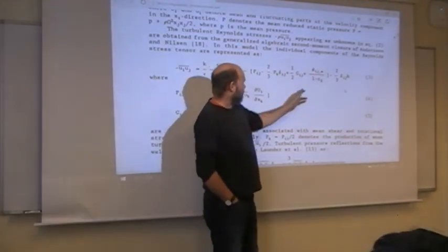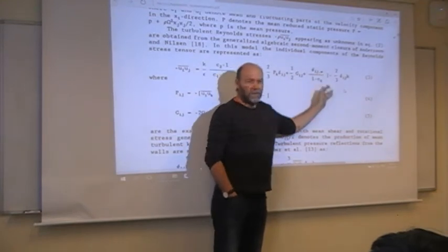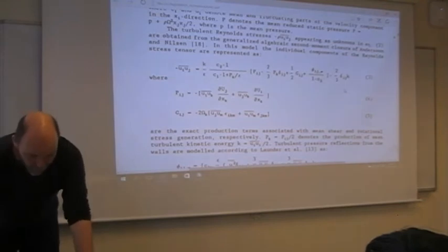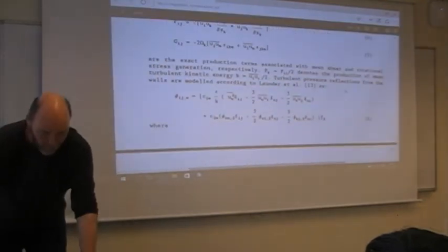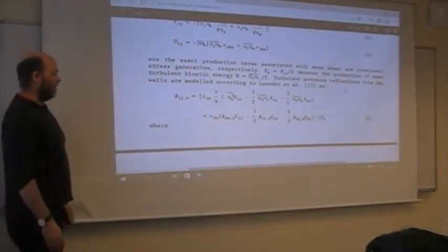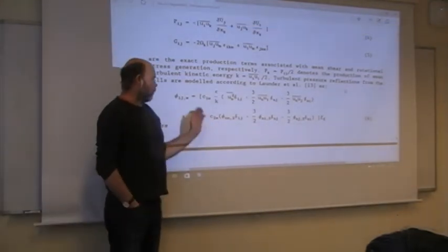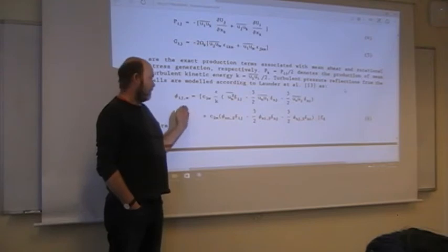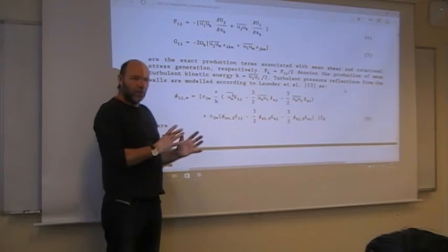Important, a wall function. It's sort of unavoidable with these turbulence models, ASM, RSM, to fight with a wall. So we have to treat the wall very carefully, very specially. That you will see in most turbulence models, what kind of wall model you will use.